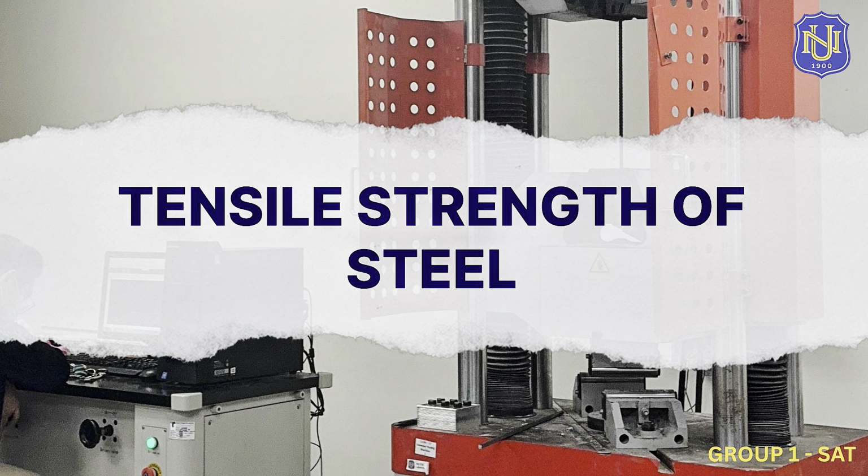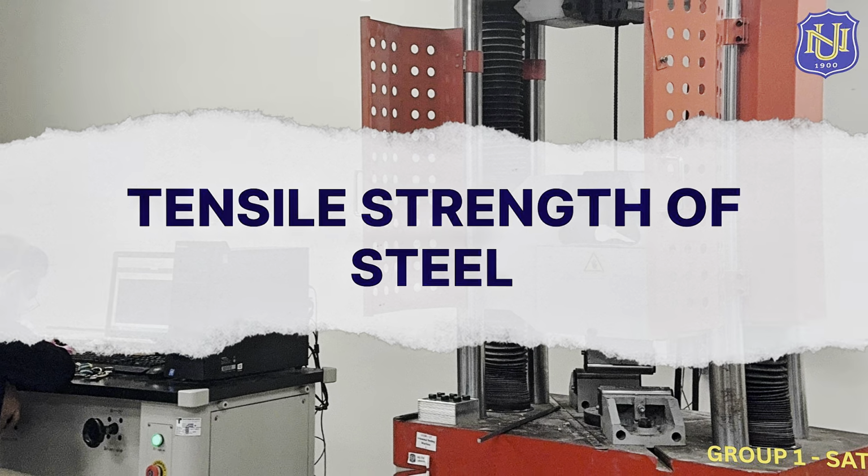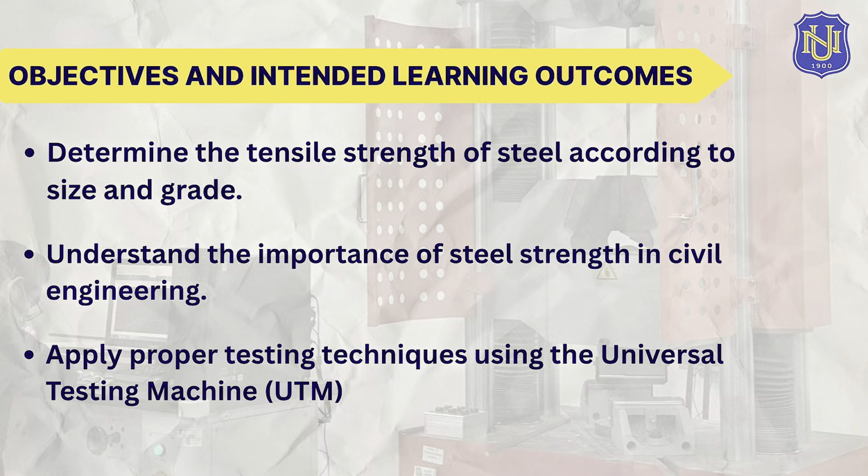In this experiment, a universal testing machine, or UTM, is used to apply axial tension to steel specimens until failure occurs. Through this test, important properties such as tensile stress, strain, elongation, and deformation behavior of steel can be analyzed. This experiment aims to determine the tensile stress of steel according to its size and grade.